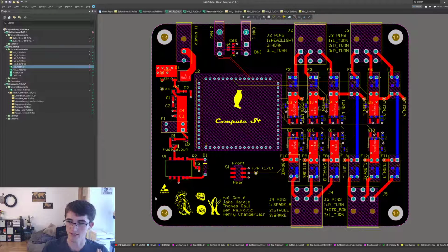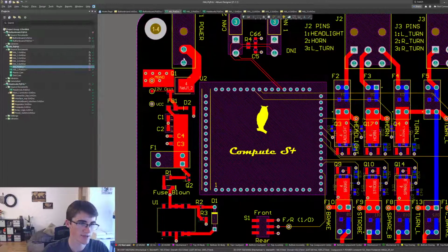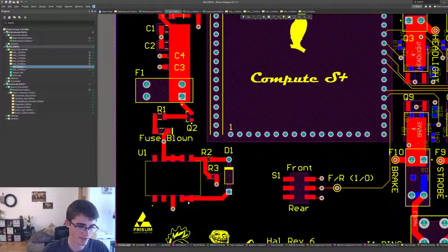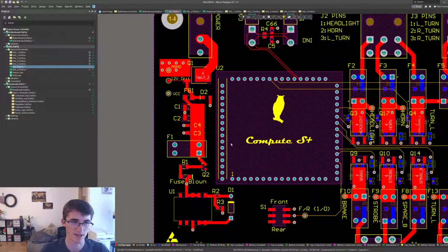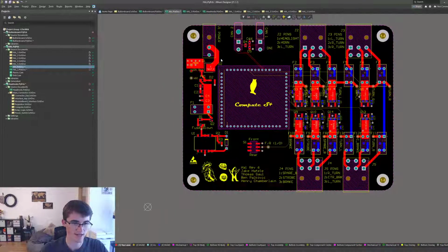This was a choice that I made just so it would make life a little easier on the designers, and it would also teach them kind of what to think about with a 4-layer board. You'll also notice that most of these current inputs are a lot larger. That's just because we're dealing with a lot more current in general. So I just beefed up a lot of the traces there just in case. But that whole power circuit is kind of the same.